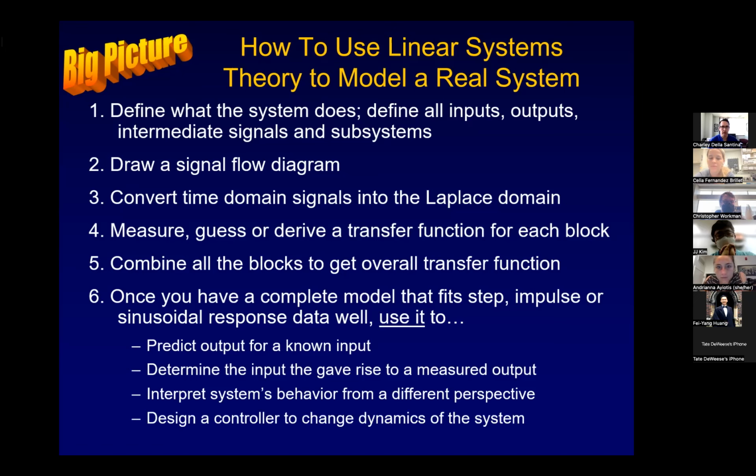Sometimes you use a model to design a controller to change the dynamics of a system. The second car I bought was a VW Passat, and the guy I bought it from had put a chip in it that adjusted what happens when you step on the gas pedal so it would accelerate faster. And all that was about was measuring out the dynamics of the car's acceleration and putting in a precompensator so that for a given amount of pressing down on the pedal, you would get greater pickup on the car, but not crash. And that's an example of designing a controller to change the dynamics of a system.